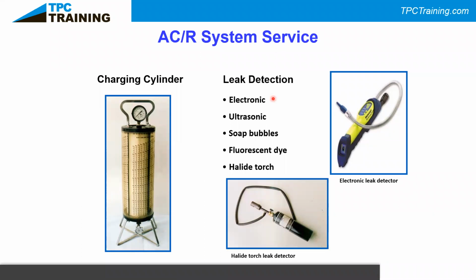And when we find that leak using an electronic leak detector, this will beep like a Geiger counter. It'll start to whistle at you. And when it whistles at you, it's letting you know that that leak is in that general area. It's not going to tell you the leak's right at that spot. Ultrasonic, the same thing, general area. You literally put headphones on and you take a sniffer and go around and listen, and where you hear a whistle, you know that's where it's leaking.